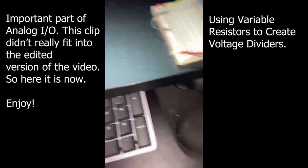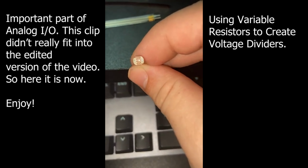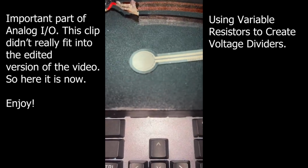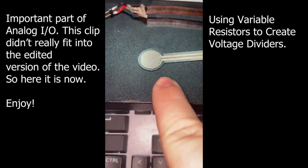But this one is a photoresistor, so as you shine more light onto this, the red portion changes its resistance, so it gets less resistive the more light is on the component. This one, the round one, is a force sensitive resistor, and as you push on it, it pushes around the little bit of liquid inside of there, so that way more electricity can flow.